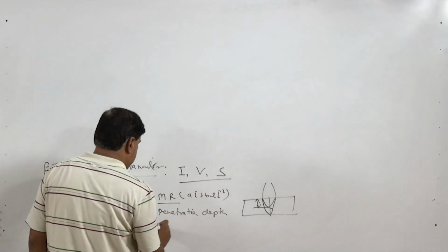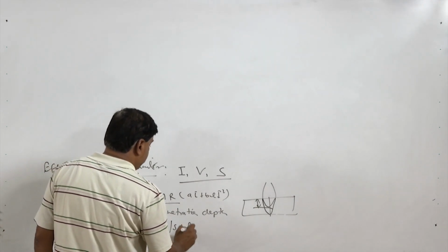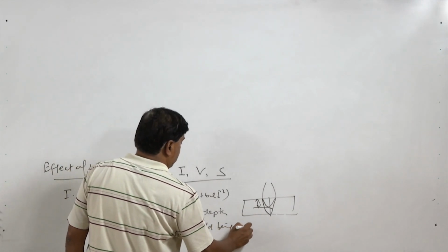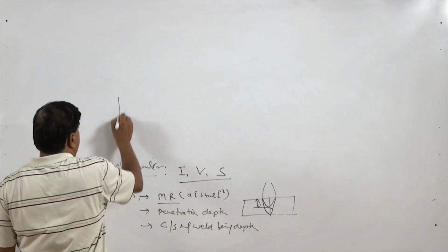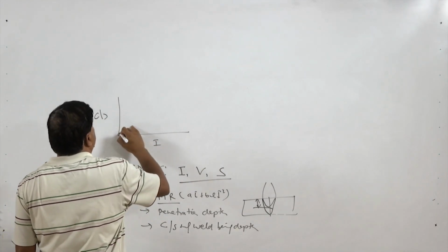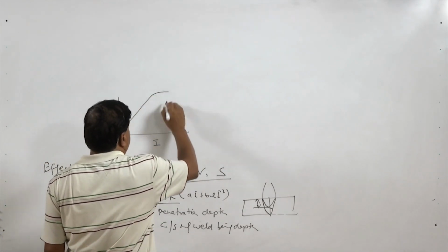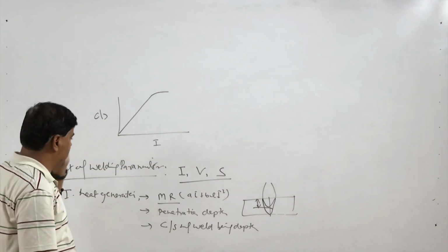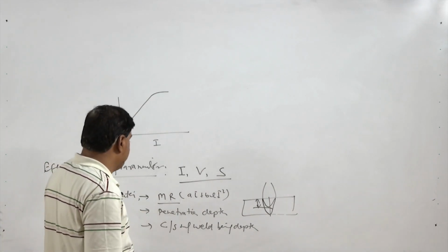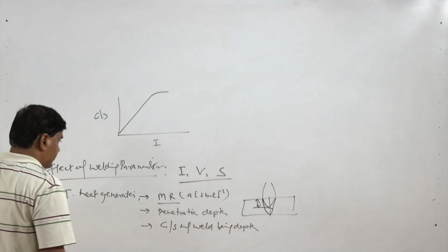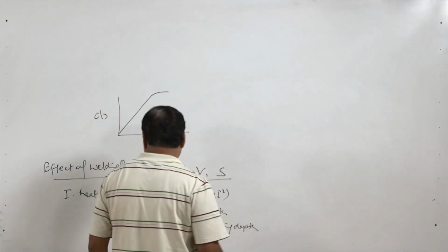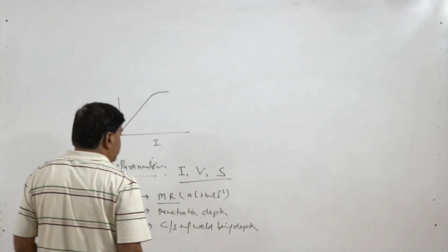It also affects the cross sectional area of the weld being deposited. Increase in current in general increases the cross sectional area, like if we plot current against cross sectional area, it increases linearly and then starts getting flattened, or the slope starts decreasing gradually. So, these are the three important factors related to the effect of the welding current.